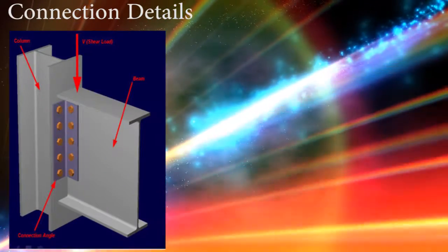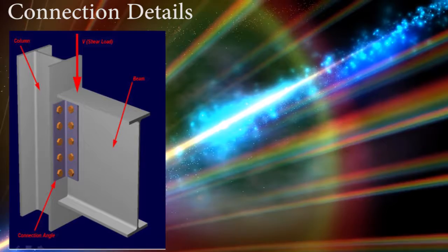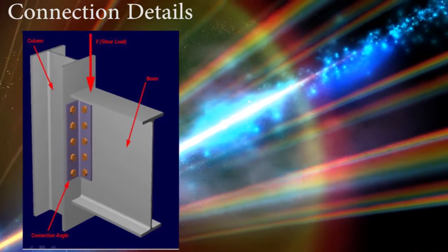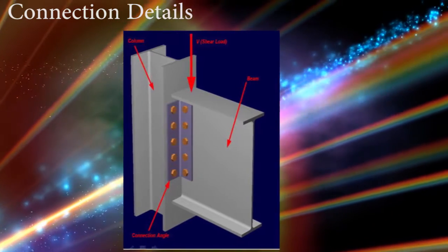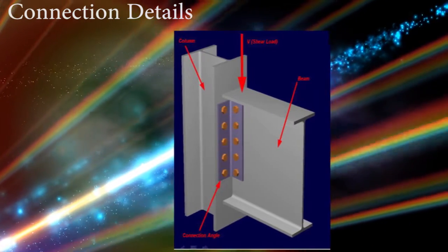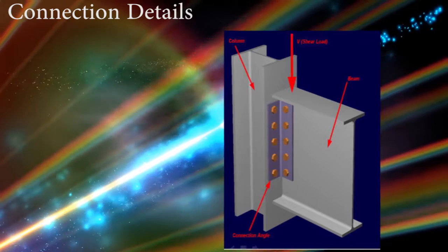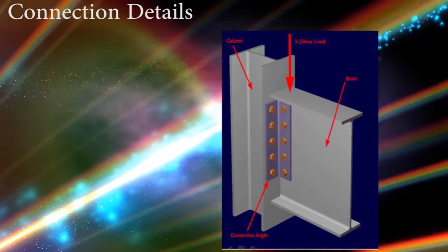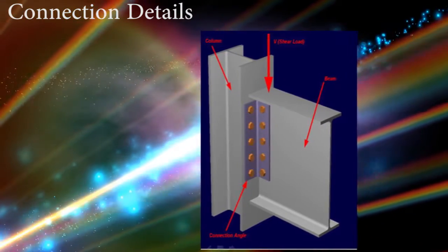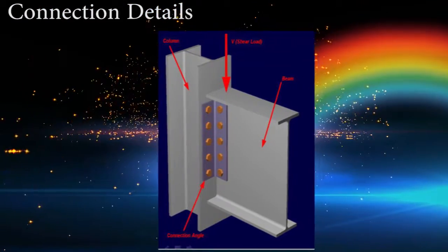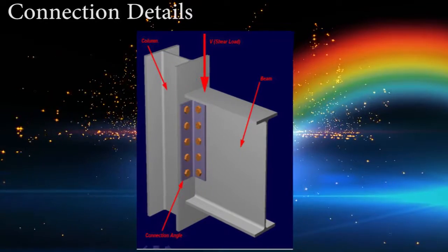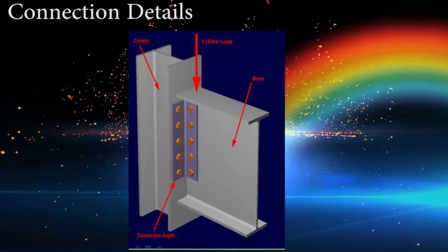Connection details. A. Shear connections. Beam checks all properties, for example bolt bearing. B. Interconnector checks bolts, welds. Connector checks shear rupture, block shear, bolt bearing. Connector to support checks, if bolted, same as checks on beam to connector. Support local checks, bolt bearing, if column web, V1 plus V2.